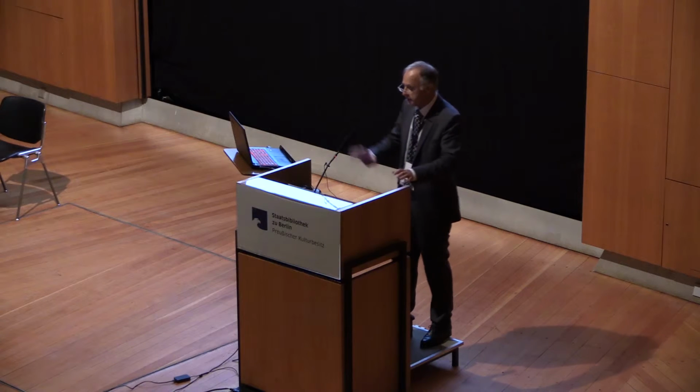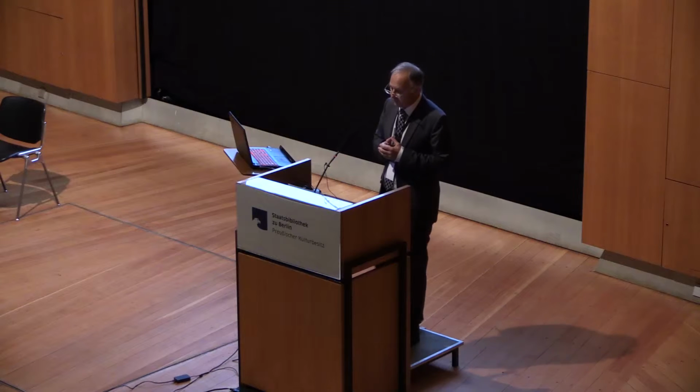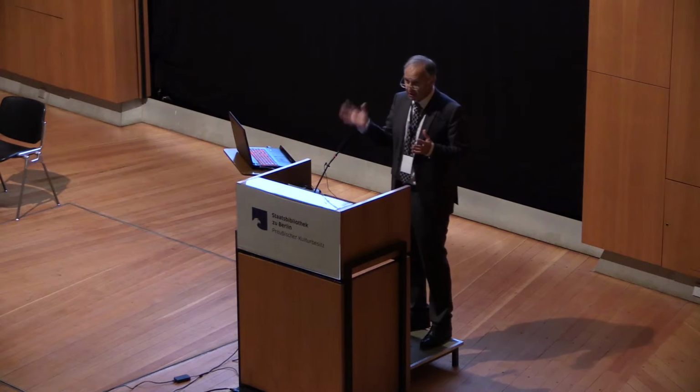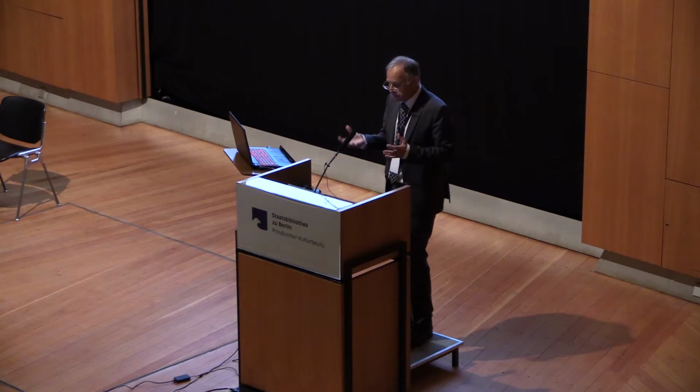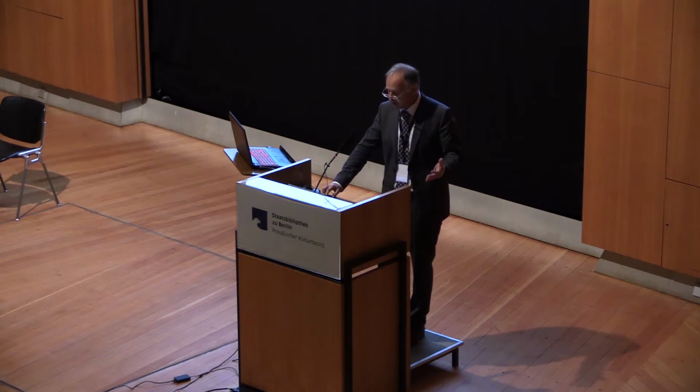So the dense image matching, just to explain it to you, is a very sophisticated approach where we have to minimize an energy function, and this energy function is just the difference in gray values between the left and the right images, and there are some penalty functions integrated. And so finally we find the right image match for every pixel. That means pixel by pixel is matched, as you see here, and finally we can use all those matched images to come out with a very robust solution in object space.